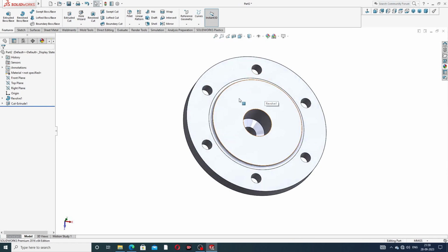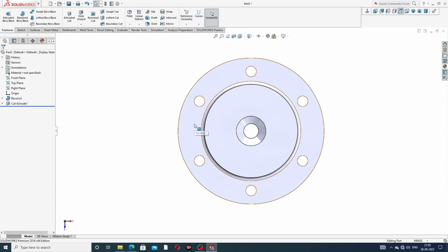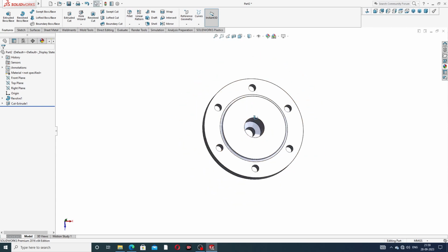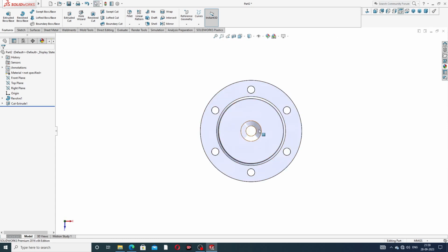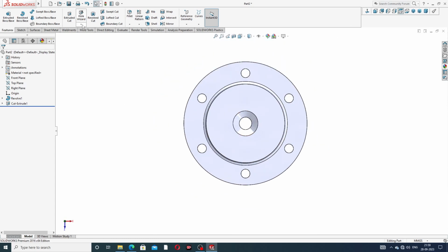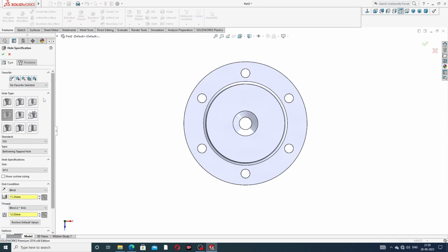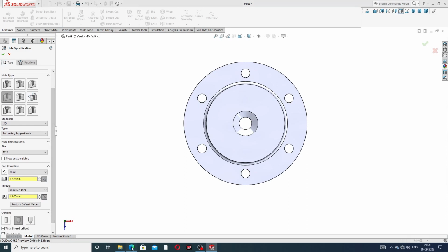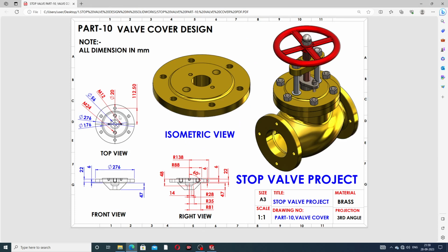And Hole Wizard is applied here, and select this face, Sketch. Okay, not mentioned, but this is Normal. Okay, and this normal is perfect, and going to Hole Wizard. In Hole Wizard use this Tab. Tab is perfect, and at first select these 2 holes. First and second, the 2 holes: one size is M24, and the other size is M12.